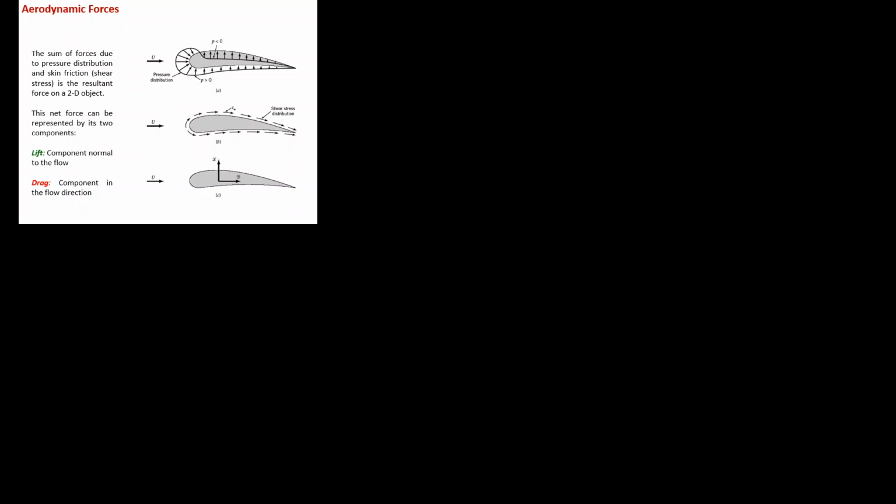We'll be looking at the stagnation points and airfoils. Stagnation points, we are not going to focus on the stagnation points. Why? Just because it would relate to the whole lift and drag forces. How would you relate the stagnation point to lift and drag? Depending on your angle of attack, where your stagnation points are, you can have different variation in lift or drag. But you essentially are relating lift and drag to the angle of attack, right? Right.